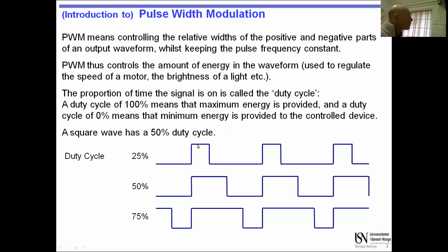So first of all, we need to make sure we know what we mean by pulse width modulation. So imagine the voltage is 0 or 5. All of these waves are in some regards called square waves, because they basically form a square shape. But a true square wave has a 50% duty cycle, which means it's 50% off and 50% on in terms of time.